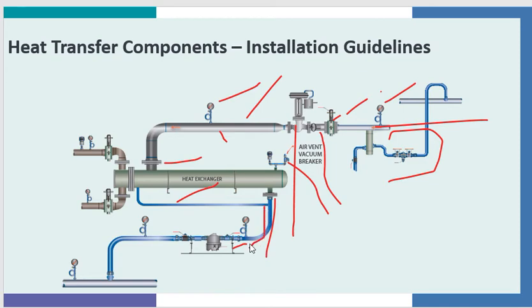This piping coming down here, this outlet is 1.5 inches, and then the piping should come to a 1.5 inch steam trap. And then making sure the steam trap is sized correctly. Go through the procedures, and we have a best practice on the selection process of steam traps and sizing of steam traps. Again, we utilize ball valves for isolation.